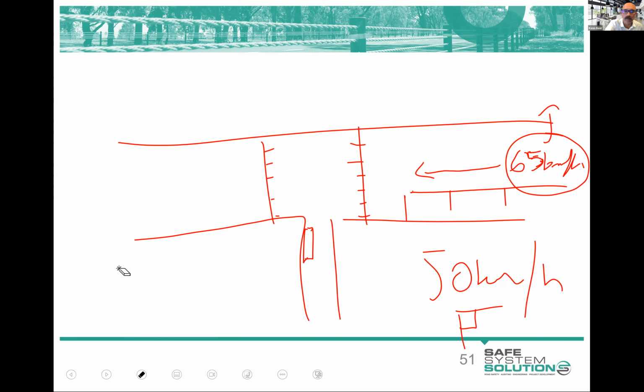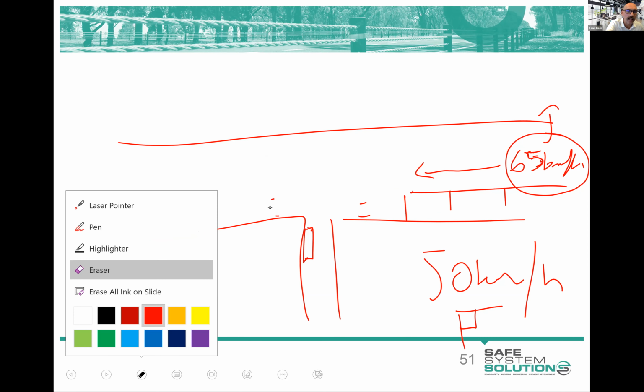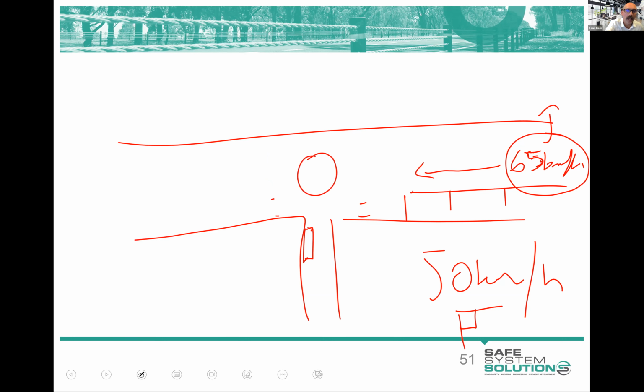It could be, as I'm seeing there, a roundabout, because if we had a decent roundabout in here, you are just not going to have this right angle crash happening at speeds that can kill and seriously injure. Okay. And that's the particular crash we're interested in. So you might say, well, a roundabout, what about bikes? What about pedestrians? That's not the particular crash for this finding.